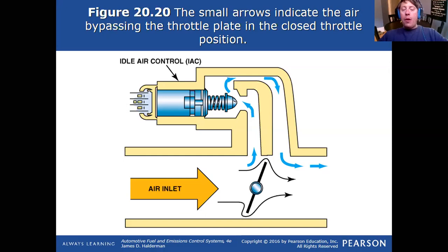And so the power steering pump is going to demand some horsepower in order to spin that pump. And the engine will have a tendency to be pulled down in speed. So idle speed control systems have like an anti-stall theory in how they work. One of their purposes is to make sure the engine doesn't drop too low in RPM.